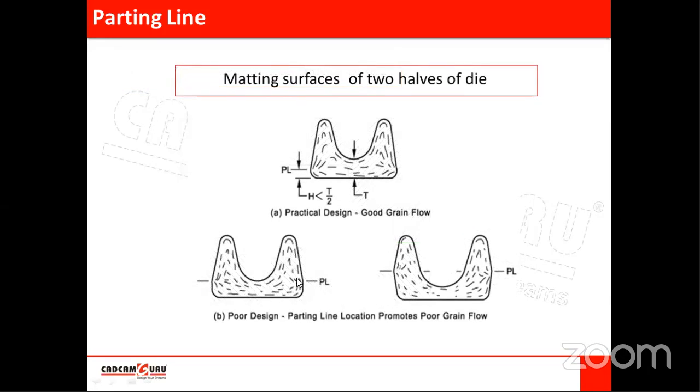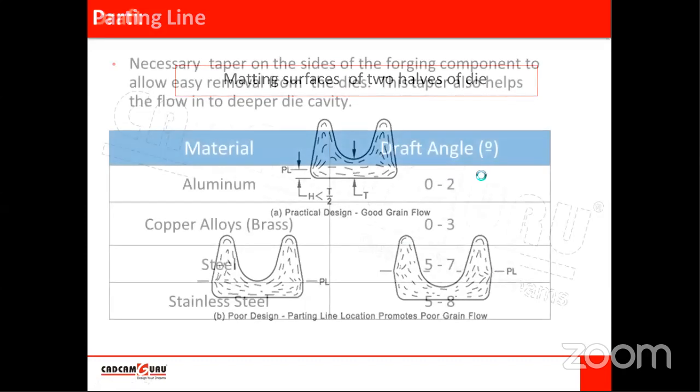So these are the poor locations, poor designs you can say. You cannot place parting lines in these areas. You have to place it in the maximum material area.